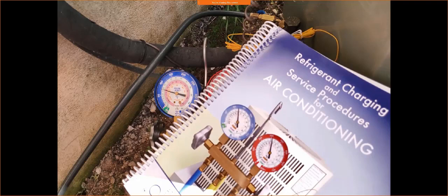Sometimes things happen, the system starts operating a little bit differently, things get plugged up, so maybe the condenser is actually dirty, all right, and so now we're not removing heat, and all of a sudden we're getting a greater subcooling effect. So there could be various reasons, but you want to make sure that your air filters are clean, your condenser coils are clean, everything's operating like it's supposed to, and there's no blockages.